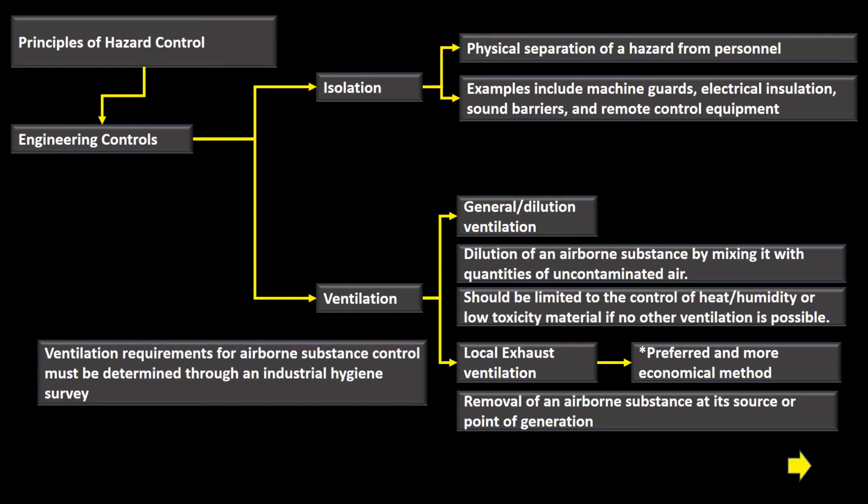So any ventilation requirements, you're going to get those requirements through the industrial hygiene survey, right? Every command, ships included, has an industrial hygiene survey, and they're supposed to have a current survey on board, and that will determine what type of ventilation is used in what type of space.